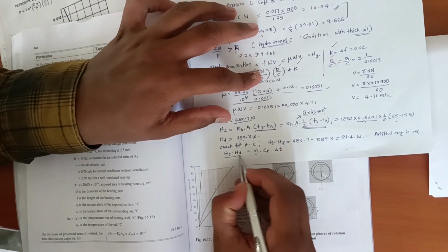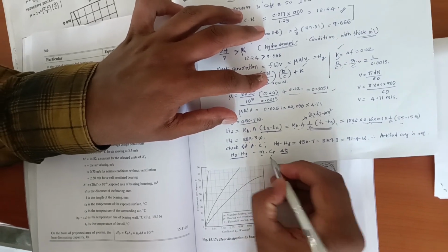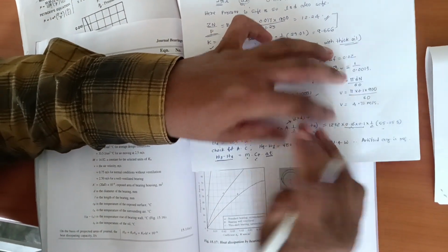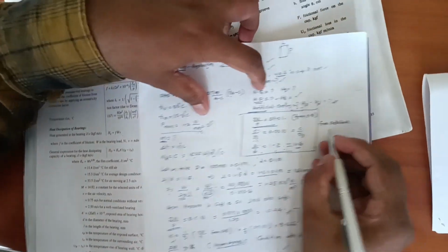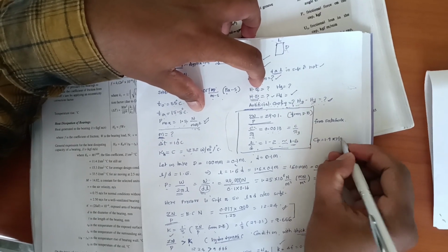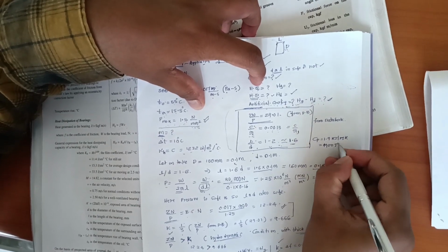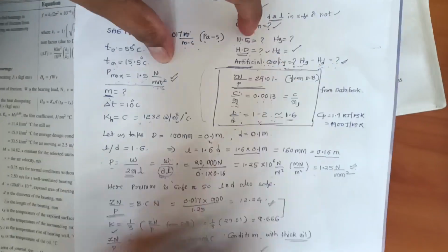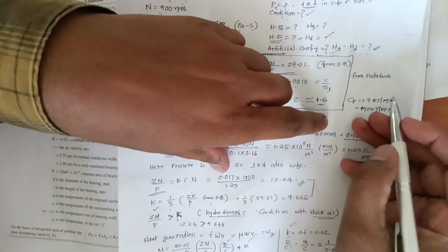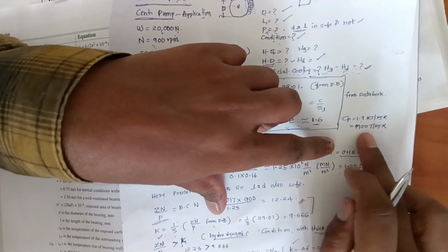Okay. So here you have to find out this m value. You know already this difference. Delta T also given, but Cp value is not given. So here you have to assume Cp value is 1.9 kilojoule per kg Kelvin or 1900 joule per kg Kelvin. Generally as you know we have Cp value 2.1 kilojoule per kg Kelvin. You are taking 1.9. You can take 2.1 also. Let us take 1900 joule per kg Kelvin.